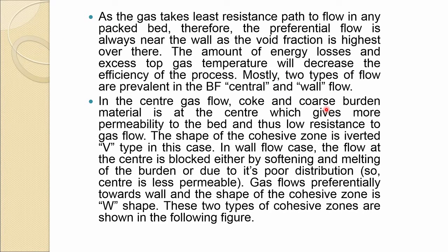The other thing is, as the gas takes the least resistance path to flow in any packed void, the preferential flow is always near the wall as the void fraction is highest over there. The amount of energy losses and the excess top gas temperature will decrease the efficiency of the process.